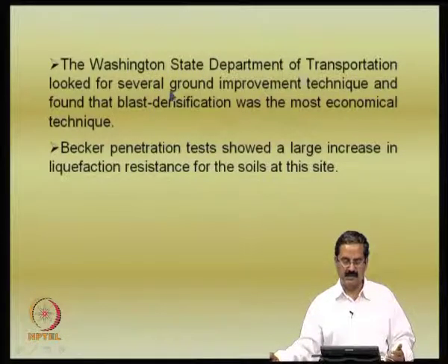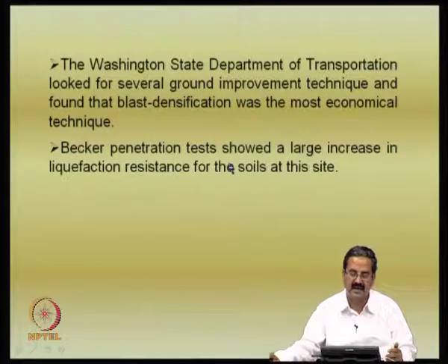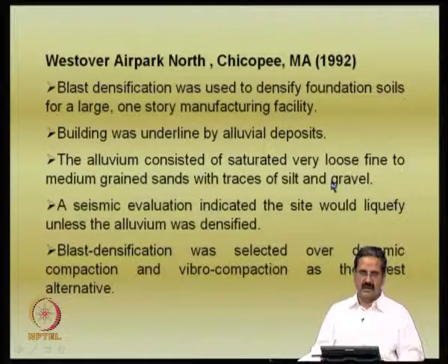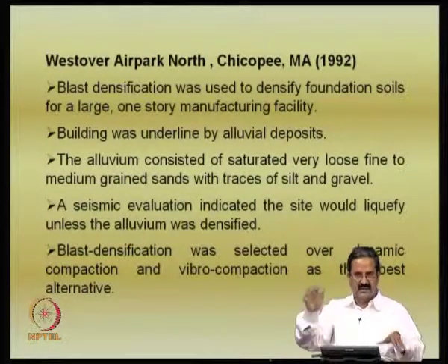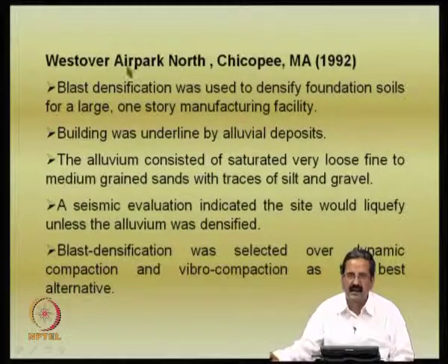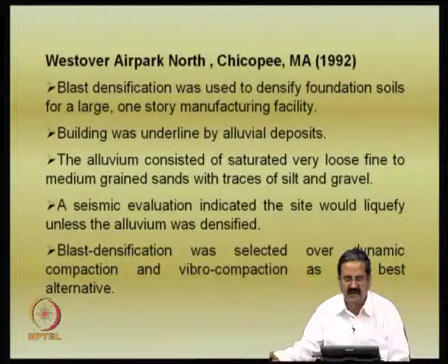The Washington State Department of Transportation looked at several ground improvement techniques and found that blasting was the most economical technique. They did some Becker penetration tests, which showed a large increase in the liquefaction resistance of soils at this site. They did a lot of analysis, including cost analysis as well as the feasibility of doing the work at the site, and when they could see that blasting was effective, they went ahead with blasting.